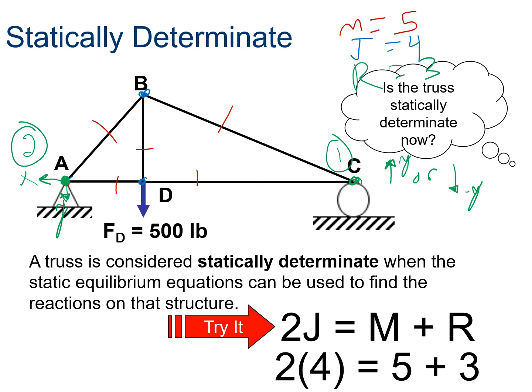And so what that does is, why would we want a rolling support? Well, it's really when you drive over a truss like this, you want to make sure it doesn't rotate. So you really need vertical support. But you also want to let the structure breathe. Breathe under certain temperatures and pressures and things of that nature. Otherwise, like I said earlier, you're going to have some pre-stressed materials that aren't going to behave very well under static or dynamic moving loads. So this allows, for something like expansion joints, allow bridges that span certain things to be able to kind of move closer together or further apart based on the temperature, especially here in Chicago.